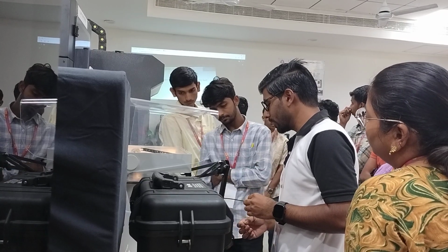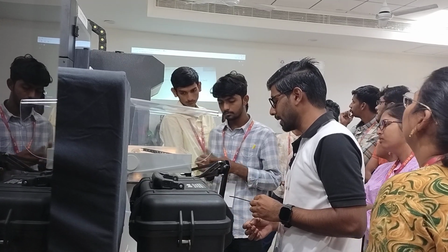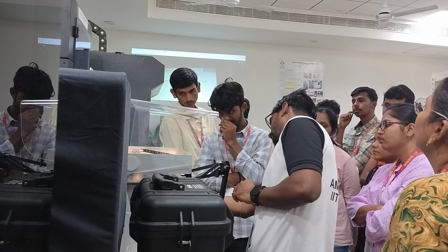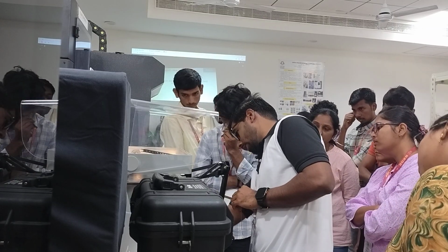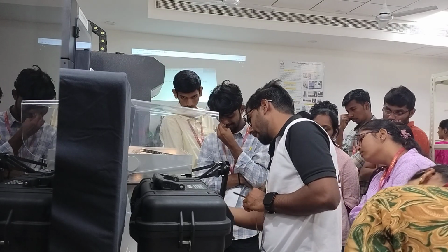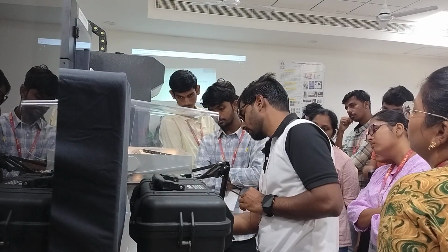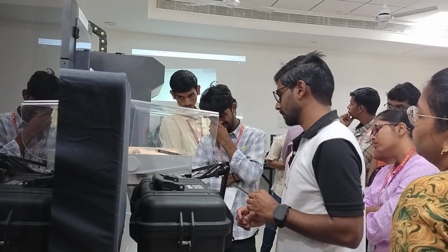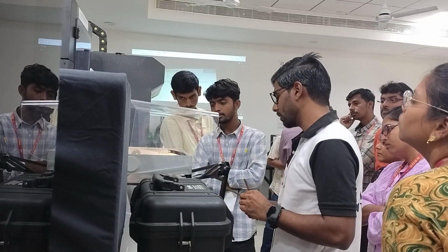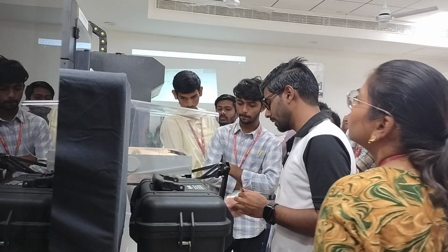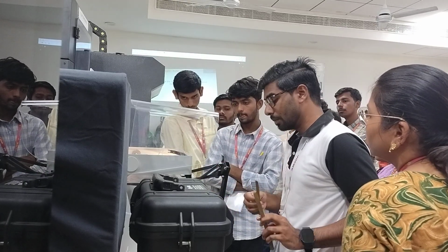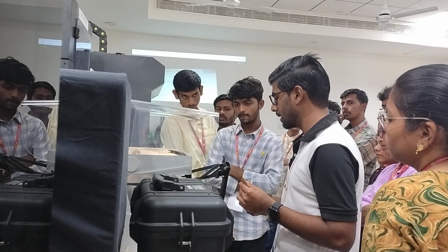I click. Loosen the thumb screw until the print bed is at its lowest position. I have already done that. This is a thumb screw, and 3 thumb screws are there. I loosen them so that the bed is at its minimum position. Then I'll click next. It is moving to the right position. It has moved. Now it is telling me to place the plastic shim between the print bed and the plastic nozzle.